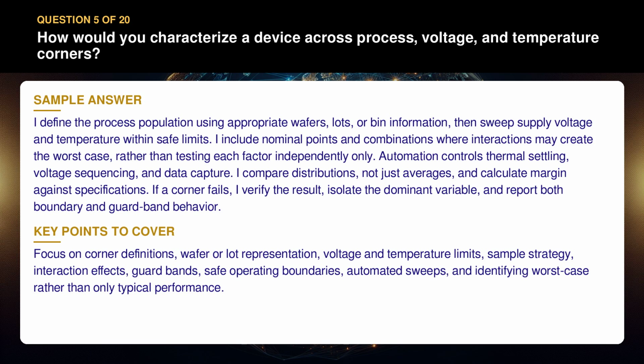Focus on corner definitions, wafer or lot representation, voltage and temperature limits, sample strategy, interaction effects, guard bands, safe operating boundaries, automated sweeps, and identifying worst case rather than only typical performance.